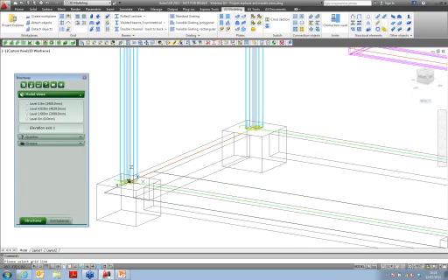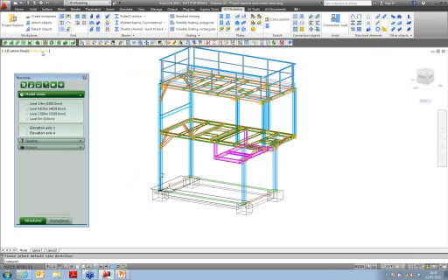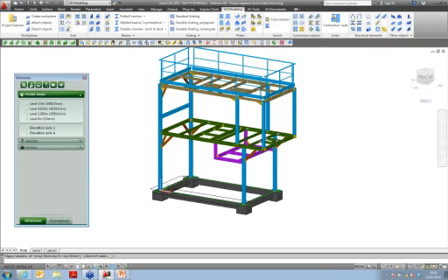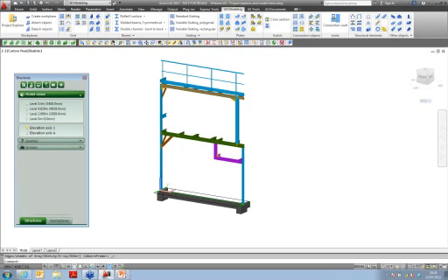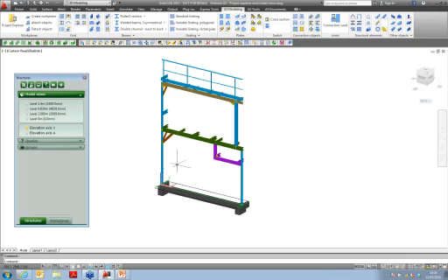I would like to pick this grid line, A, press enter, enter a name, elevation axis A, and now I get some arrows. I can pick this one because I want to see from the outside. And now it's very easy. Maybe I can show you in realistic mode. Okay, it's very easy here to pick a model view, and you get only the elements which are in this model view which are displayed at screen.